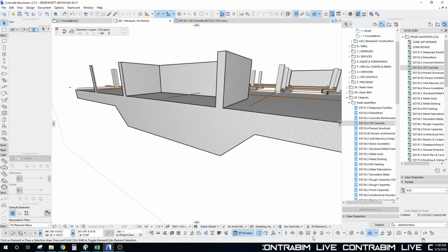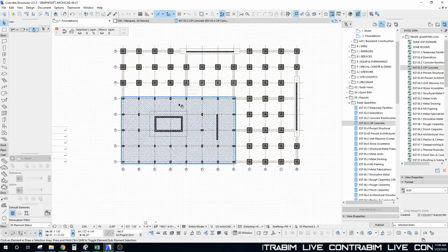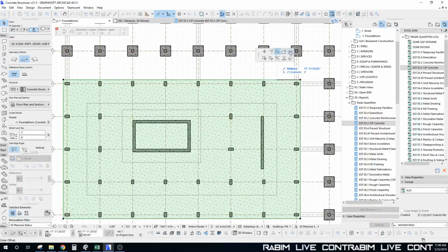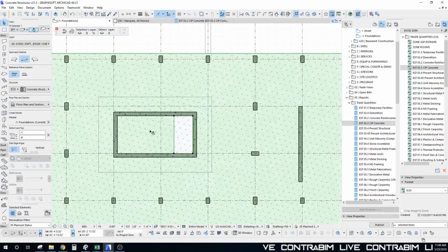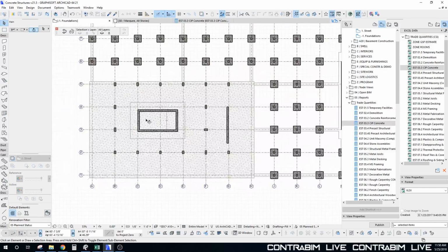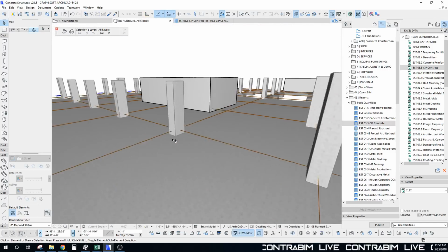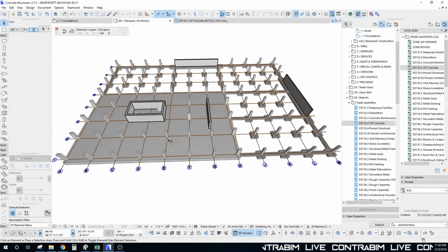A lot of the time your entire mat will be sloped slightly if you're trying to push your methane out to the sides or to collect it. So one thing to do is we should probably cut out that space here out of our initial mat. Let's cut that out for our elevators. So let's make this maybe just 10 feet, which is probably deep enough for our elevator pit. And let's see in 3D to make sure that shows up just right. Okay, there we go.